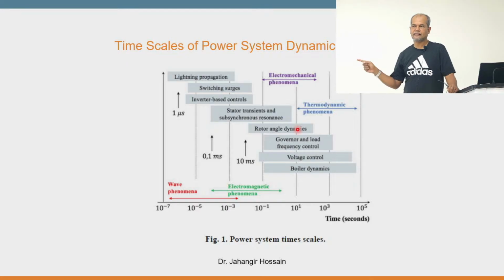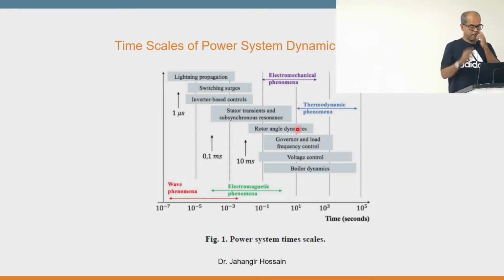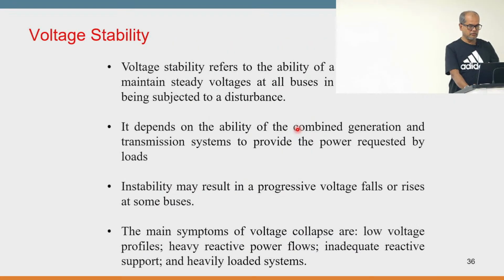PSCAD can do electromagnetic. So be careful: if you are trying to show inverter dynamics, you shouldn't use a simulation that does not capture the dynamics of the system you are using.